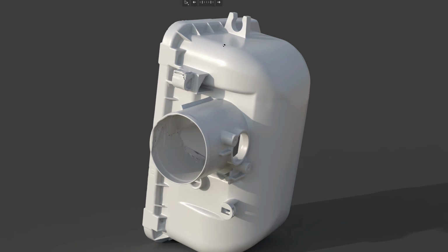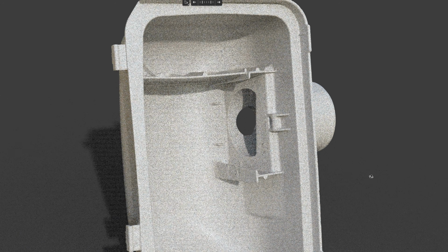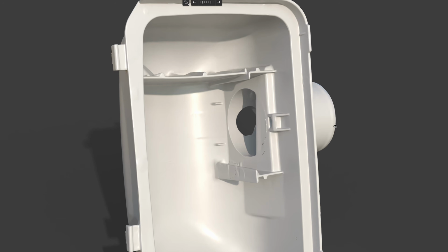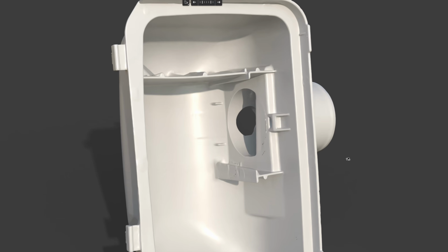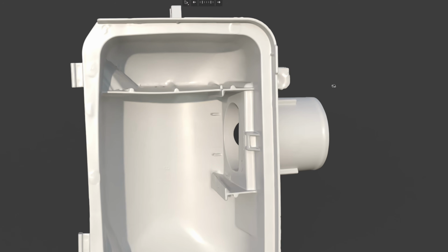As you can see, there are stiffeners along the mounting flange to increase the stiffness when it compresses onto the air filter. And from the inside, there are 3 stiffeners, 1, 2, and 3. These stiffeners strengthen the part when you insert the air hose, so the wall will not flex too much. And there is also a partition inside of the airbox, but it's sagging down. I don't know why it's sagging down like this, if they did this on purpose or if the part has deteriorated.